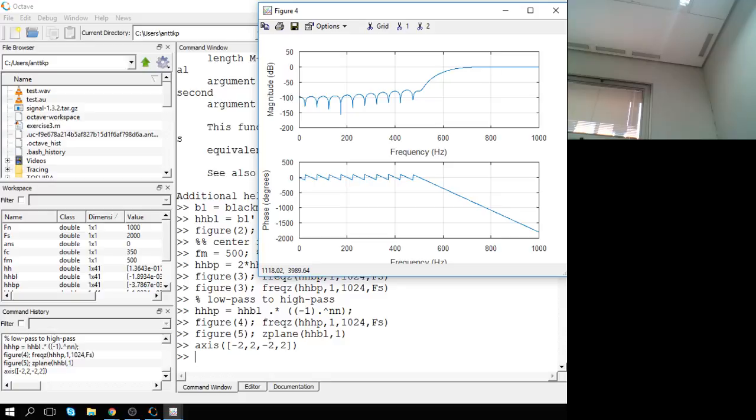If you really want to have a different order number, then basically you need to align the filters so that if the other one is wider, you add filter 1 and filter 2 in the same place. So what you are adding? Well, you are adding the impulse responses in the time domain. Okay, so that's how you match different length FIR filters, for example, to make the band stop filter.